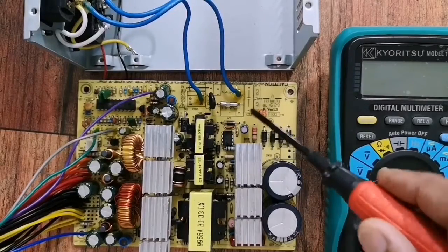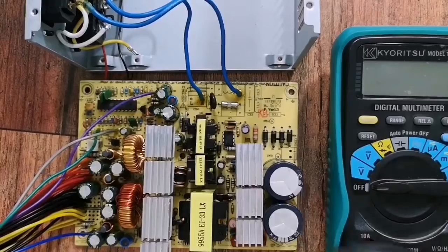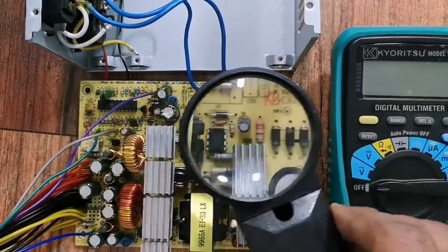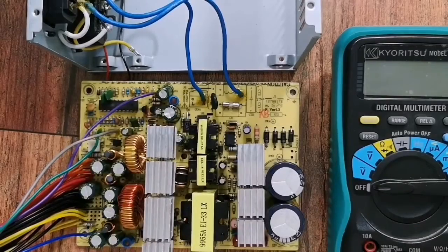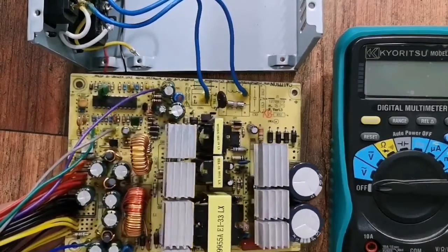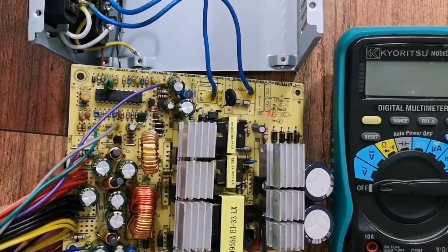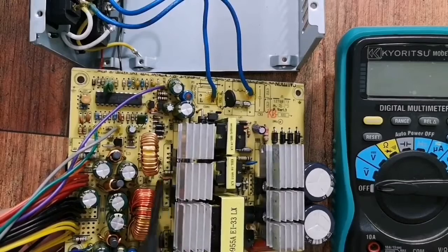Normally, very fast I start by checking status of fuse and do some visual inspection to see if any visible faulty component can be located. The second step, while the circuit is power off, I just check for short circuit in all these big semiconductor components.